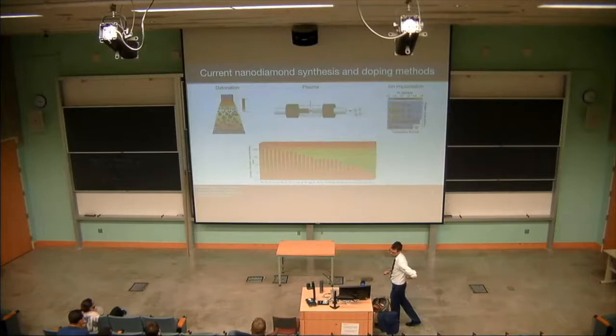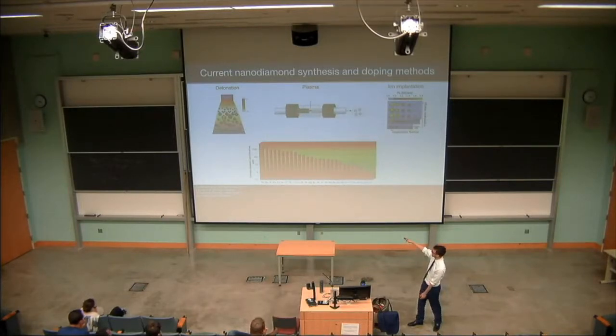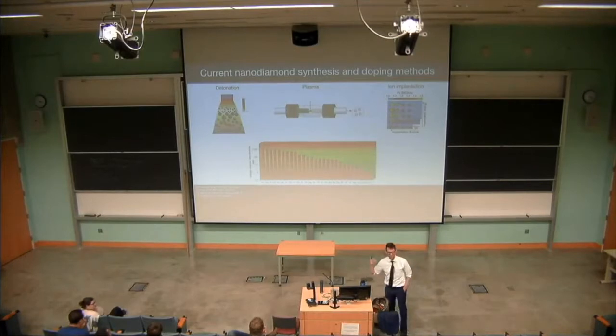The primary way of making nanodiamond, there is one, fortunately. There are a few different pathways. One is actually detonation. It's a way of getting rid of old TNT. They can take TNT in the presence of random carbon precursors, ignite the TNT, and then within the shock wave, you tend to nucleate small domains of nanodiamond. You can intentionally dope the nanodiamond this way, but you also seem to accidentally put in a ton of the periodic table into the sample as well. And so again, getting 4 elements or 5 elements on one lattice site, completely out the door.